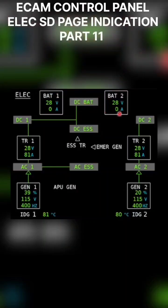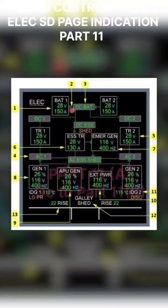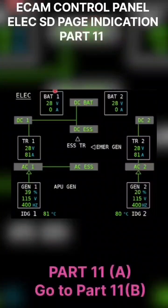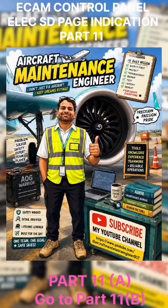Here you can see two batteries are connected to the DC BAT bus, and if they need charging, when they are fully charged, the battery charger limiter will disconnect them. So this is your battery charger limiter, which will show the discharging indication. Once it has discharged, it will go out from the ECAM view. So this is all about the normal configuration or in-flight configuration.